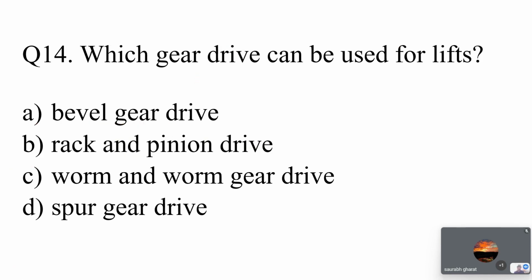Which gear drive can be used for lifts? Again, this is an application based question. So from various points, what we actually need for lifts is the part here. So what is needed for a lift? Again, the power should not be transmitted from output to input, because if a sudden power cut happens, you should not have the case that power is transmitted from output to input, so it suddenly fails and the lift goes down. This should not happen. There must be a kind of locking mechanism if there is a sudden power failure.